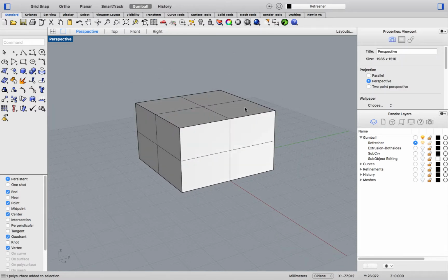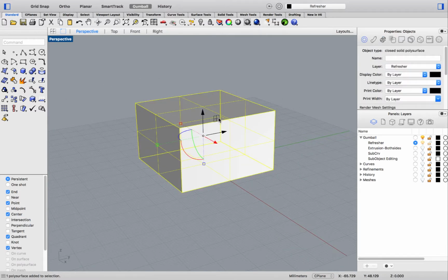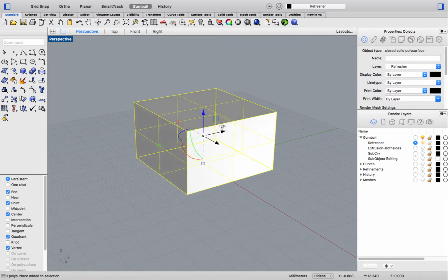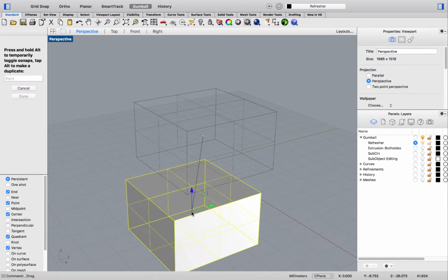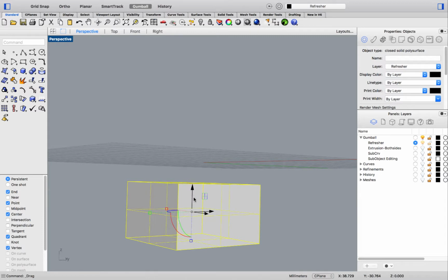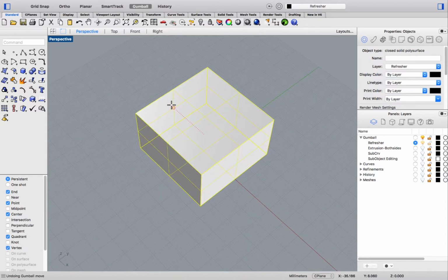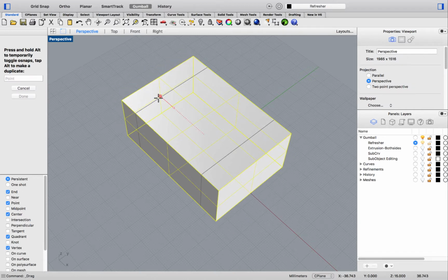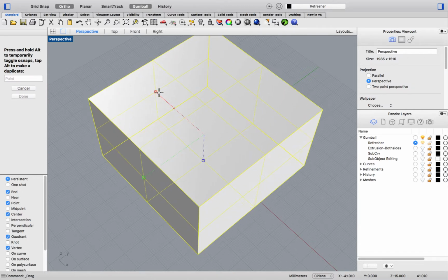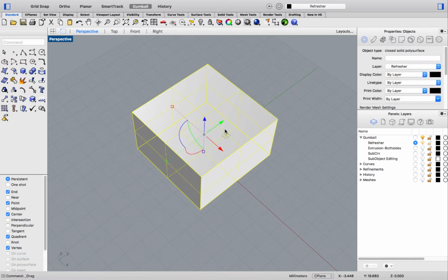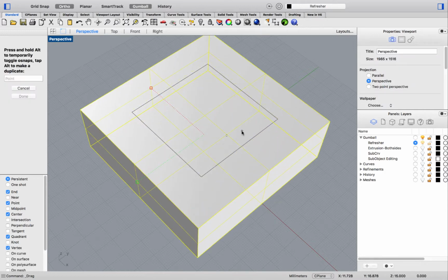You'll also notice that different planes appear as I move and rotate the view around. These planes will allow me to move my object in two directions. If I pull on any of the square handles, I'll be scaling 1D. By pressing the Shift command, I can scale in all 3 dimensions. We can also scale in 2 dimensions by pressing Shift and pulling on the plane icon.